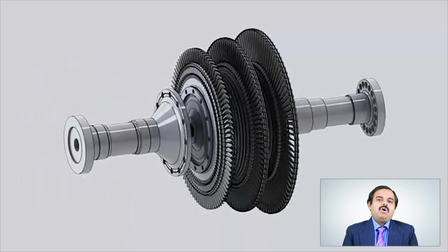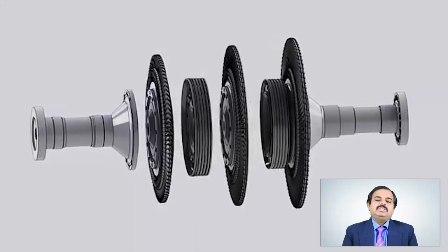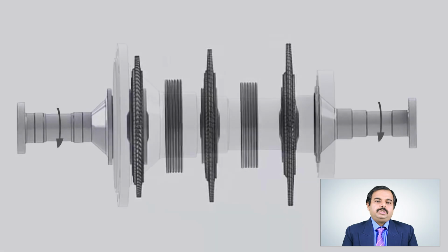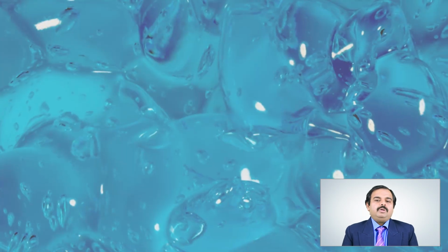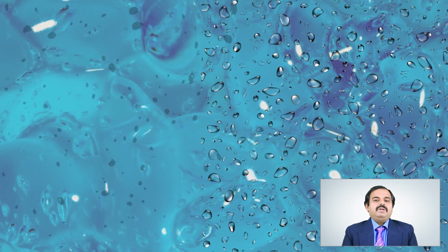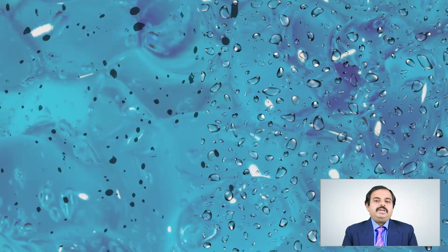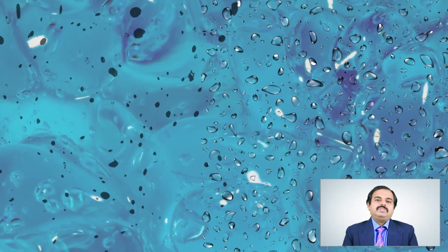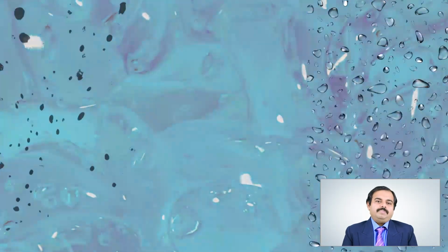The design of the bearings and the selection of oil viscosity coupled with the shaft speed go hand in hand with the necessity of hydrodynamic lubrication. The ability to separate water and prevent rust necessitate the importance of anti-rust additives and inbuilt ability to separate water.